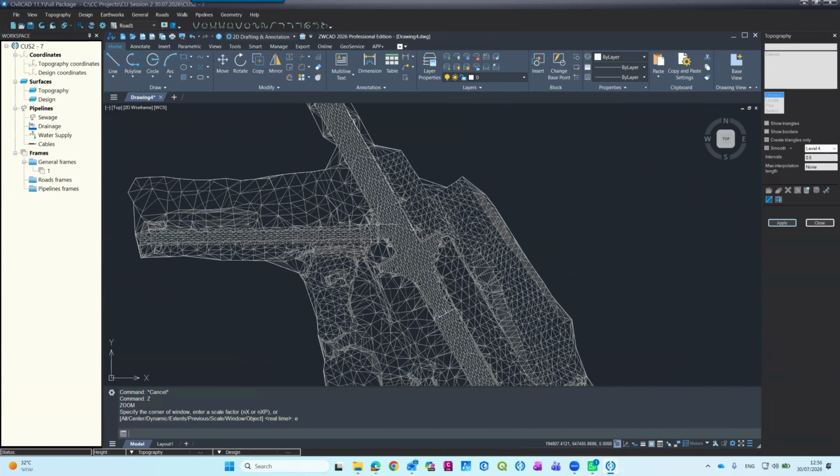In CivilCAD, if you want to create it, you stand on the surface, you right-click, and you export to LandXML. So, for example, if I do the project that I did before, I can do the project, create, fine-tune my surface, go here, export to LandXML, and then give it to someone, and he can continue his design or volumes calculation, whatever he wants. He doesn't need to do filtering, he doesn't need to do anything. He just uses the LandXML file.